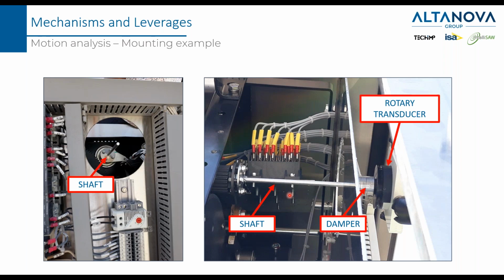So what you really need to pay attention to in the beginning is to do a survey: what is the type of breaker that you are going to test, and can you do the mechanical coupling, or do you need something else. For example, you don't have the shaft and you have to find one. Long story short, before doing a motion analysis, please verify that the mechanical coupling can be executed.